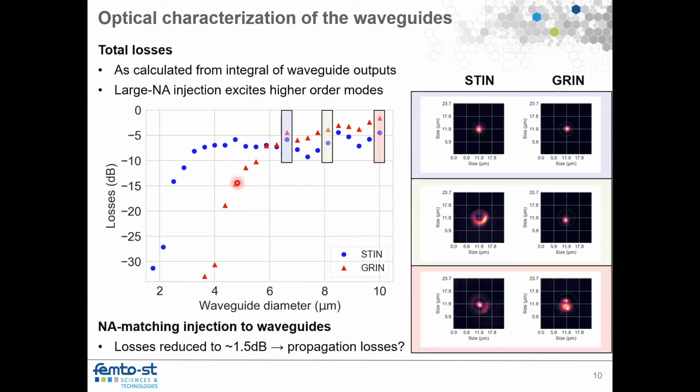In the graded index it starts later, and this is consistent with the information I gave you before for single mode fibers. I show here 3 cuts because it's interesting to see the output of the modes, since I think it's quite clean and gives illustrative information. Here, when we are still in one mode, so the fundamental mode propagating in the 2 fibers, the step index and the graded index.